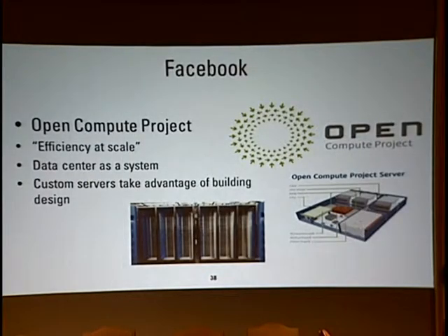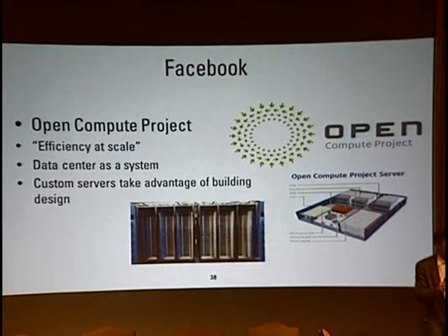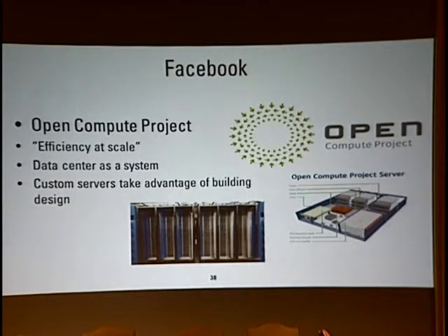It's great. Facebook has done an interesting thing with their technology. They've decided to open source their data center design. How many of you have heard of the Open Compute Project, right? It'll be interesting to see how successful they are. They've shared system designs, rack designs, building designs. They really treated the entire data center as a system. They said power's going to come in, Facebook transactions are going to come out, everything in between works together. So they don't have fans in the servers. They pressurize the cold aisle to blow the air through the racks. The racks are specially designed. They have UPSs in the racks. They have all this stuff. And their tagline is efficiency at scale.